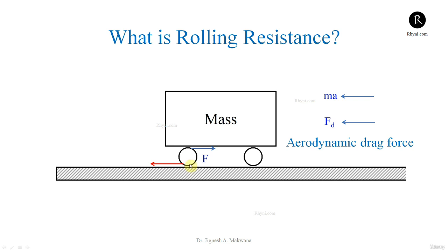And even if we consider the rubber tire and there is some deformation of the tire, then this line will become an area. So when we consider only point friction, this friction will be very less. But when it comes to line, there will be more friction, and even if we add the deformation, that means it becomes an area, then again friction will be very high.